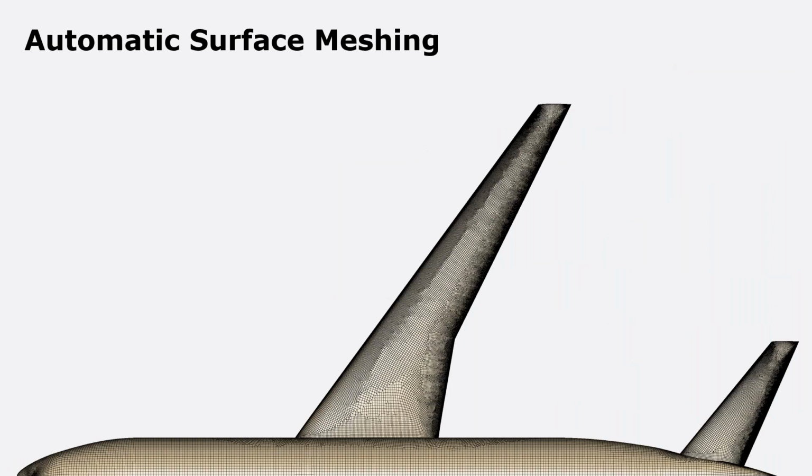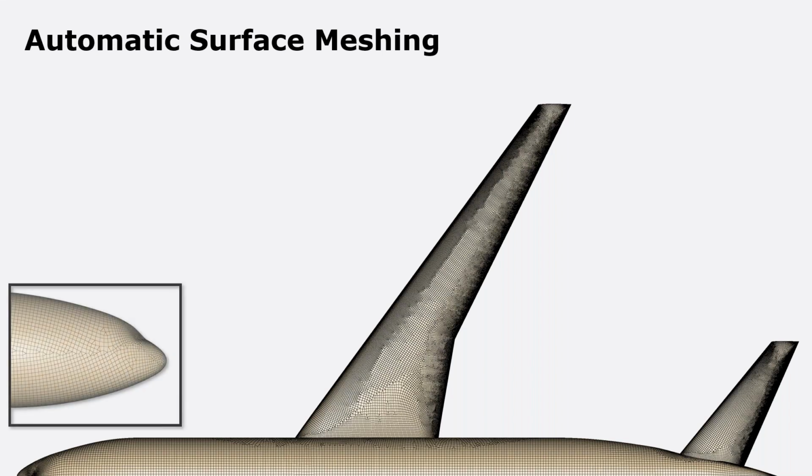All right, so now I'm going to show you some of the characteristics of really the out-of-box experience that you get with Flashpoint surface meshing. And we'll start with the alignment of the quads up near the nose and the fuselage. Like I mentioned, this was really the only parameter that we changed from the default advancing front tri-meshing algorithm to quad dominant in this case. And you can see the nice alignment of those quads on the surface.